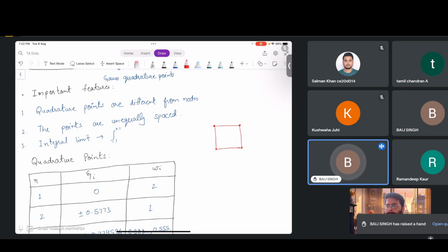So they are telling the integration points. What is that? Integration points are actually Gauss points only. If in a four node element, we have some coordinate element like this that I've drawn here, these are nodes. So the integration points would be somewhere inside. You're taking say four points only. They are actually somewhat inside the domain.